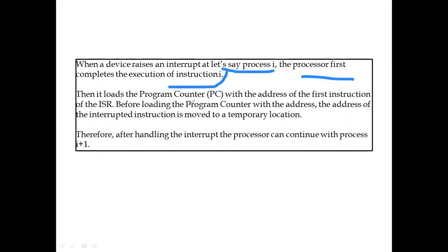Then it loads the program counter with the address of the first instruction of the ISR. Before loading the program counter, the address of the interrupted instruction is moved to a temporary location. Therefore, after handling the interrupt, the processor can continue the process I+1.